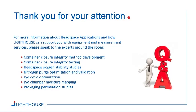Another question: if you have a liquid biologics fill at atmosphere with no headspace gas, how would you detect a leak? Every method has its pros and cons, and in fact, USP 1207 gives some guidance in how you might go about choosing a method. Obviously, if you're using Headspace, you need to have a headspace for it to be applicable.